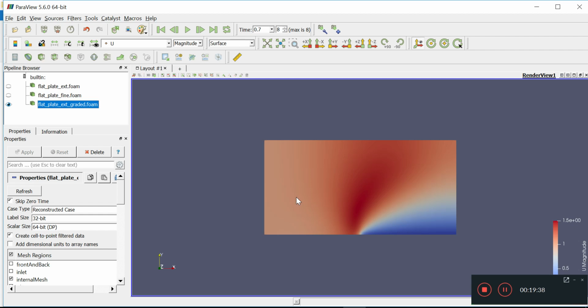Okay, so in the next video, we'll explore some other things. We know that the mesh size and the time step are just about right because the Courant number is pretty low. We have refined the mesh. We have even given it the entrance region that was consistent with what was online. So what's wrong? We'll find out more.